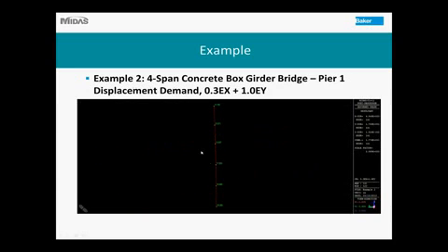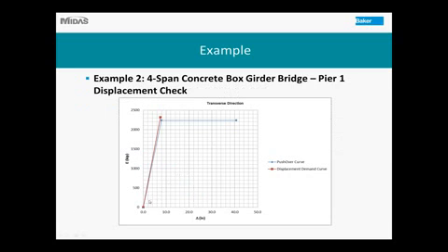And the displacement plot from Pier 1 is 17.75 inches at the top of the column and 10 inches at the bottom of the column at the pile cap level. So the foundation is pretty flexible. The relative displacement for this column is about 7.5 inches. And the pushover curve of this column is a pretty simple calculation, it's just 1 inch and it's done.